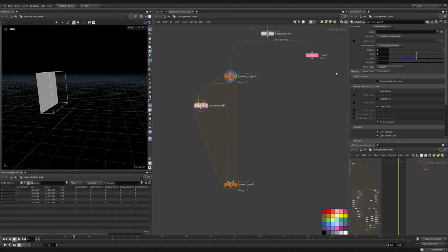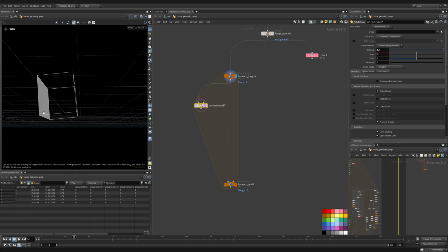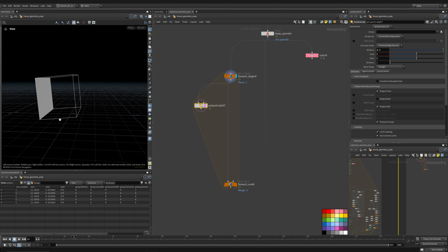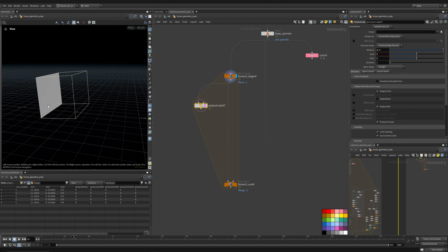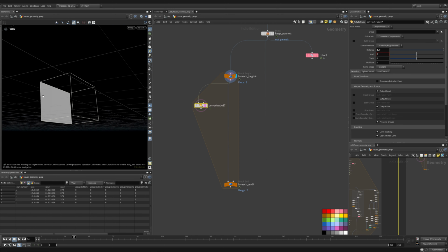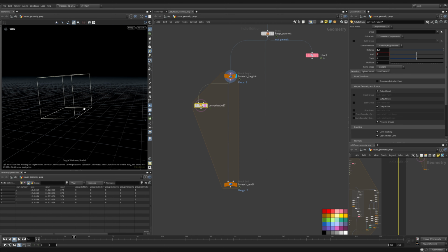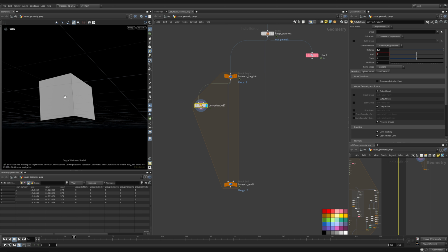Then I could push it here, maybe group normals by the base, delete everything except those bottom ones, snap those to Y, and then create geometry with that. I could also probably do a Boolean to where... maybe I'll try a combination actually. That might be a cool way to do it. So I'll start with this extrusion.